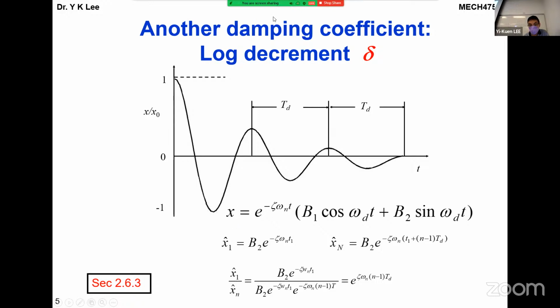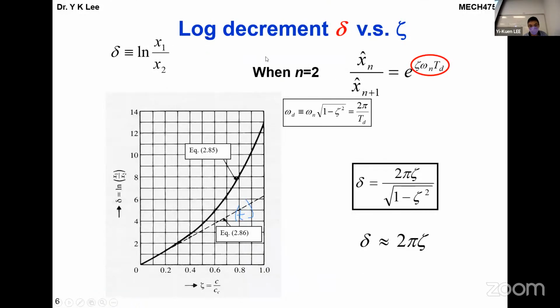Vibration and functional time can be determined in this way, right? And in this case, we can use this one to categorize this thing. Eventually, now it's clear if you can measure using a vibration sensor, right? Measure this kind of amplitude, a functional time, and pick up two peaks from the data from your vibration sensor, and then take a ratio of these two peaks, right?